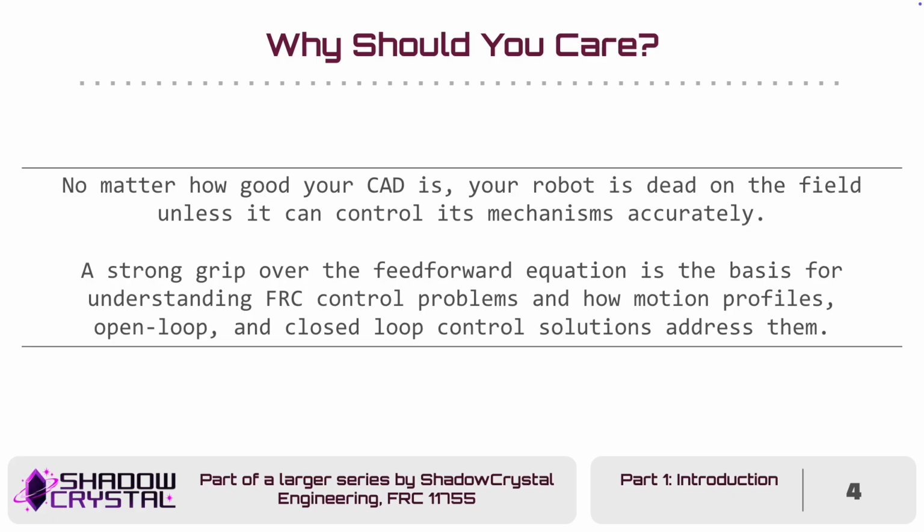And no matter how good your CAD is, this is the reason that we do control theory in FRC. A lot of times you'll just let SysID handle it, or let Krakens handle it, or let the latest and greatest Motion Magic handle it. But the reason you want to understand things at the physics level is because it helps you to optimize and tune and think flexibly and, in general, adapt your control algorithms to new external forces.